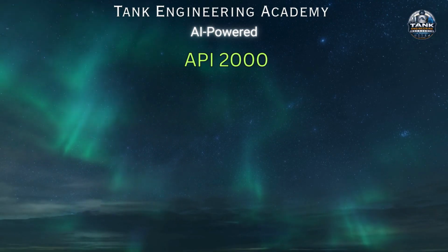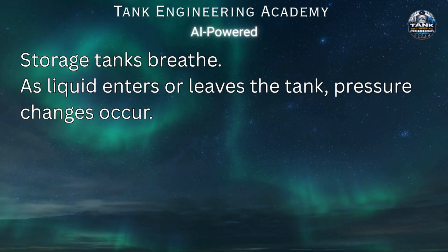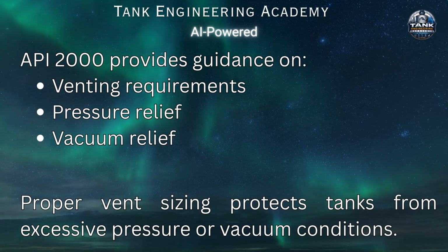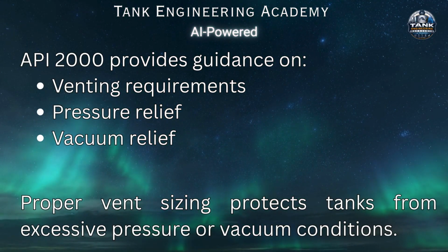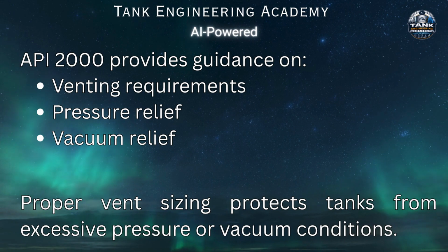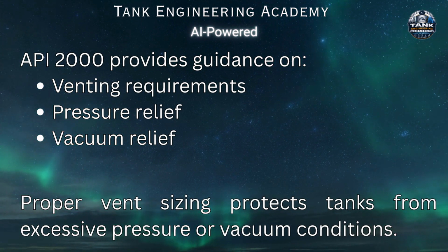API 2000. Storage tanks breathe. As liquid enters or leaves the tank, pressure changes occur. API 2000 provides guidance on venting requirements, pressure relief, vacuum relief. Proper vent sizing protects tanks from excessive pressure or vacuum conditions.